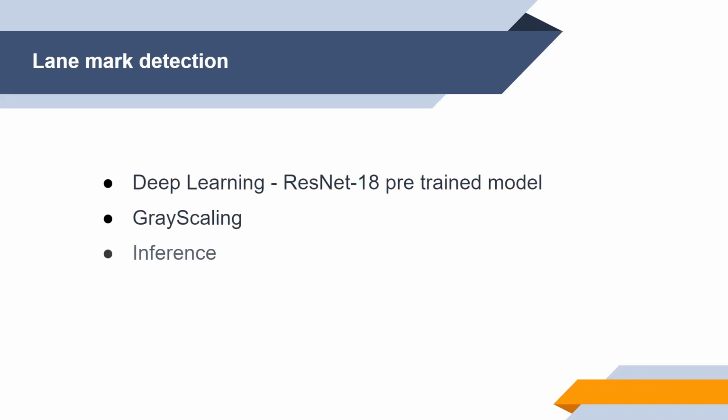Lane detection. In lane detection algorithms, a combination of computer vision techniques such as edge detection, color filtering, and Hough transforms is commonly employed to identify and track lane markings in a road scene. Initially, we attempted to use a line detection method, but it did not yield the desired accuracy. This approach detected all lines within the region of interest as lanes, including the edges of vehicles. Furthermore, our footage was unstable due to being captured from a motorbike, making it difficult to restrict the ROI. Additionally, line detection algorithms tend to perform poorly on curved lanes.